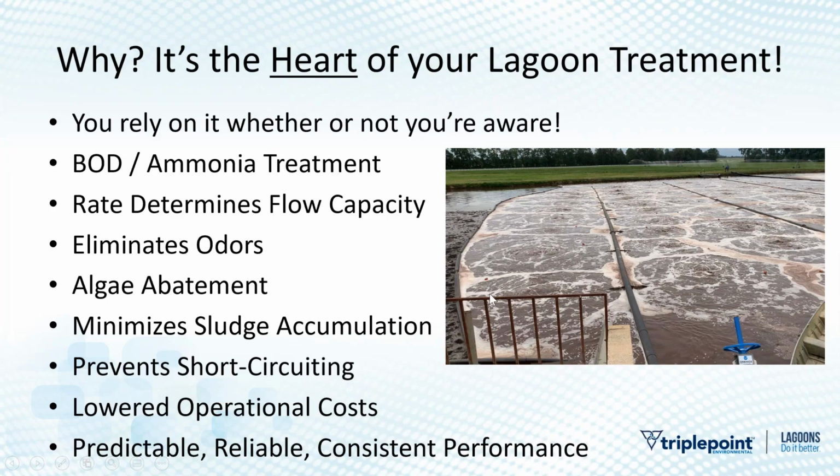Aeration really does eliminate odors as well. You'll know an under aerated lagoon as soon as you walk by, or sometimes as far as a mile away, it smells like rotten eggs or H2S, has a very smelly odor to it. If you go to a properly aerated pond, it smells just like any other pond that you might let your kids fish in. It's got this just neutral kind of musty odor that water bodies have. So a well aerated pond does eliminate odors.